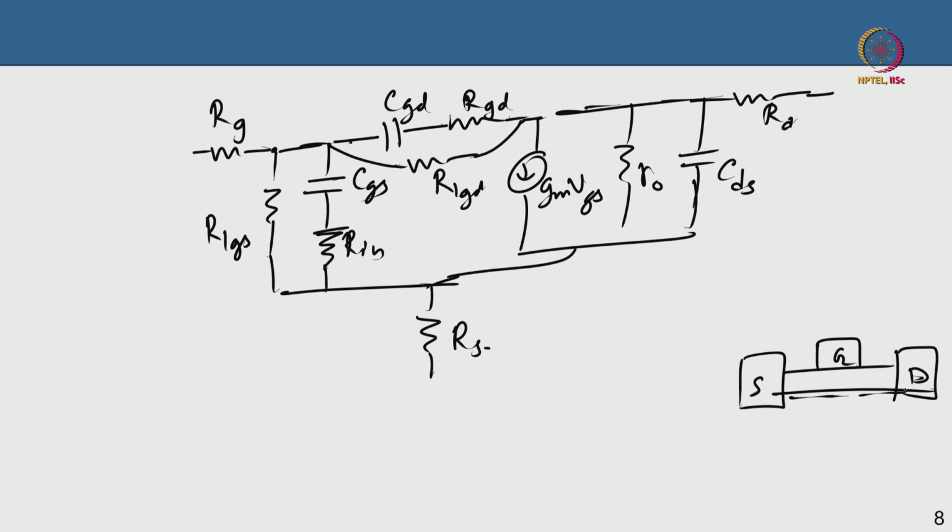Remember, in a real device, these source and drain pads will be big, especially when you have coplanars and stuff like that. Because those are giant metallic pads, they will introduce some inductance. So there will be a gate inductance, a source inductance, and then a drain inductance.